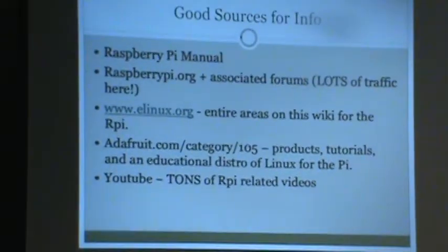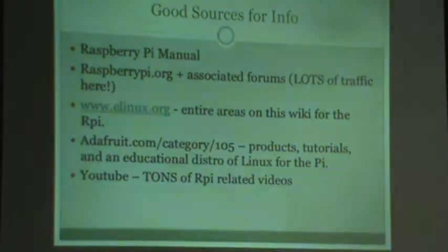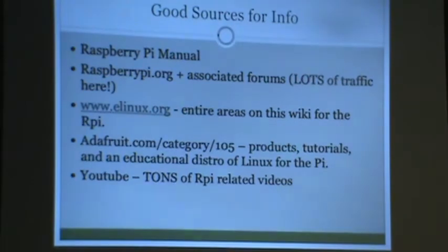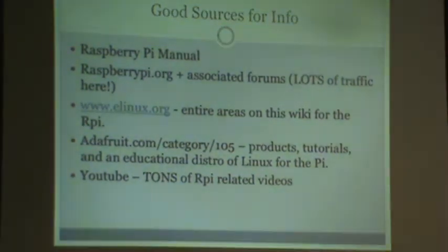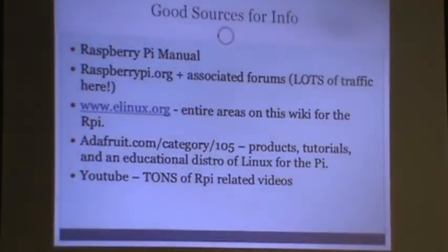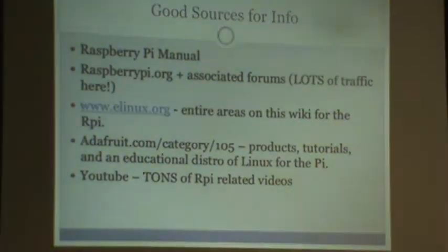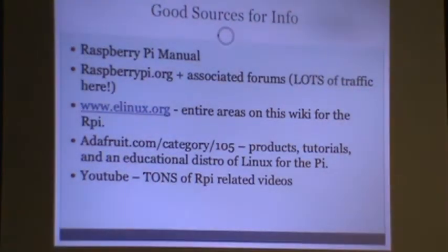But like I said, if you're going to plug in anything more than a Wi-Fi adapter and a keyboard or mouse, you're going to want a powered external hub. It has to be a powered external hub, not one that doesn't have its own power supply. Even then, they tend to be hit or miss whether they're going to work because of the USB issues they've had. They're working on getting that fixed. They've made improvements. It's something about the way the Broadcom USB chip that they chose for the board handles USB 1 traffic over the USB 2 line. I don't know all the details, but that's kind of a pain in the butt.